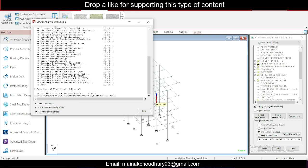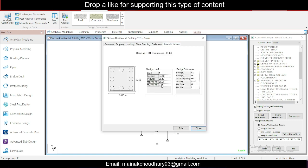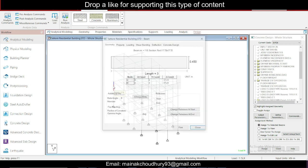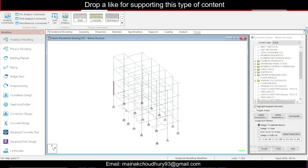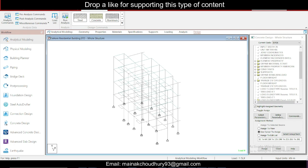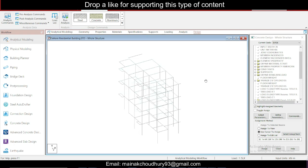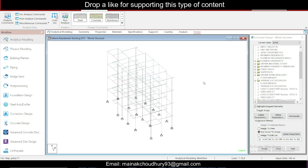49 warnings means 49 things have failed. Okay, but some members might pass. You can see here the concrete design, part size 8. I think all the columns might have passed. 8, 16, 8, 12. Okay, the members which have failed you can design here, or you can just design in RCDC. Okay, the best thing is to design these things in RCDC, right?